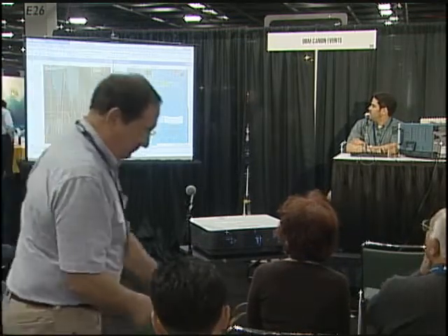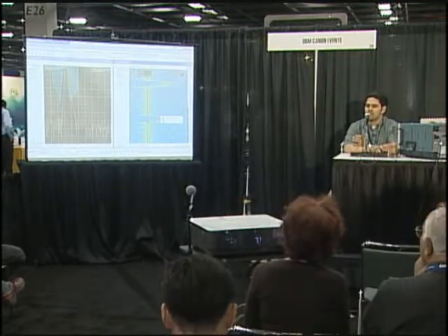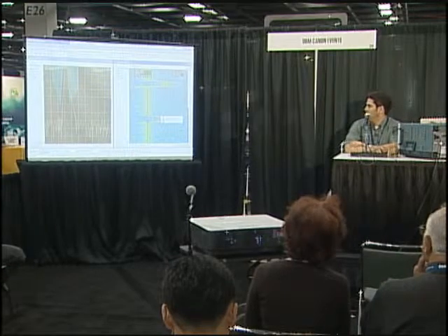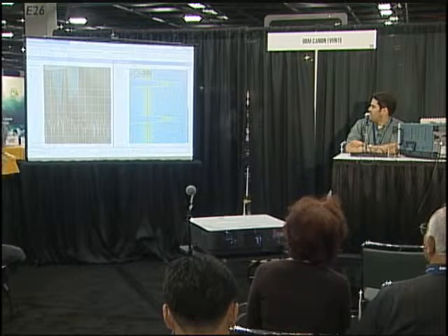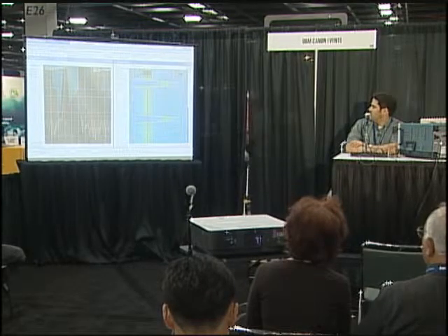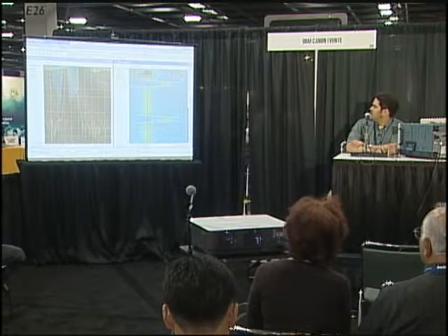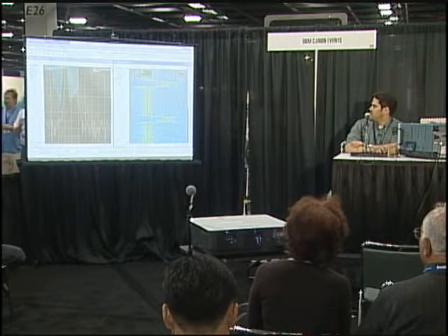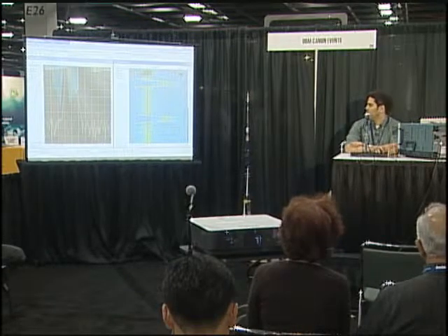Right? And then, I said that, from the DPX display, we might not get information as to how long the event took to happen or how often it happened. But we can put a delta marker, for example, between here and here. And this will measure the difference in time, frequency, and amplitude. And you can see that the time difference is 260 microseconds. So this whole activity took 260 microseconds to occur.